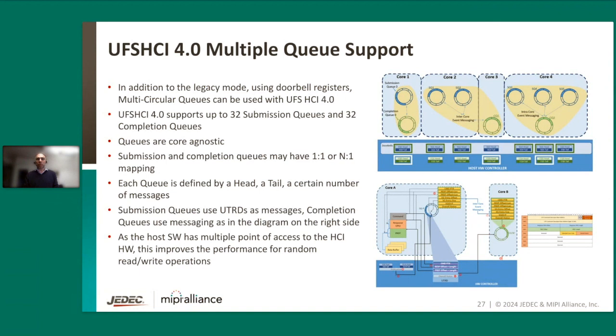If you have to transfer some megabytes of data or several tens of kilobytes, it is fine, but with small atomic accesses it was a little bit of a burden, especially as the transfer speed gets higher with higher speed gears, then the amount of time between two transactions is shorter, meaning that the host has to intervene more often, and this is not wished. So basically, we introduced some circular queues. And you can have up to 32 submission queues and 32 completion queues.